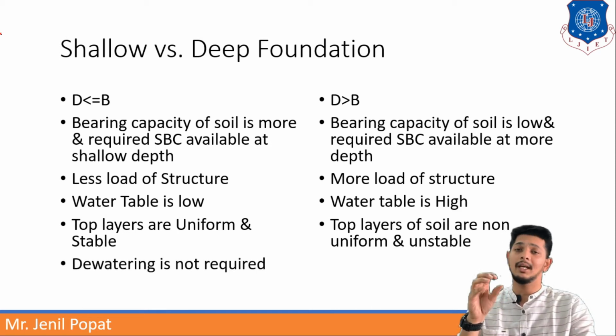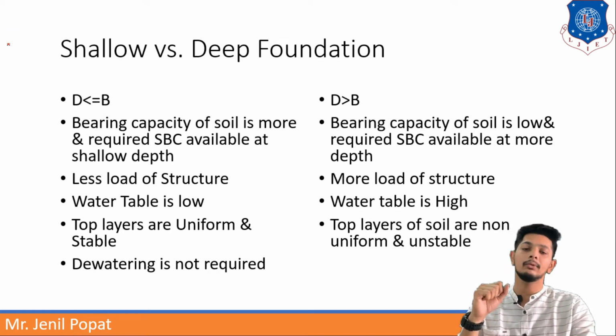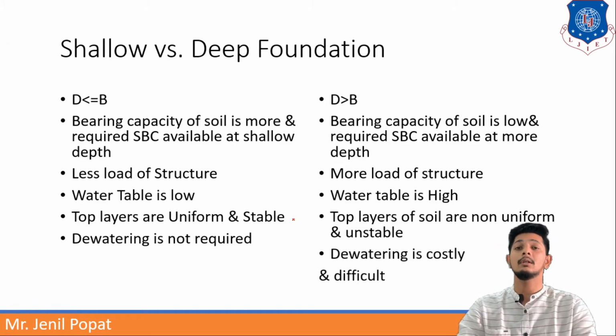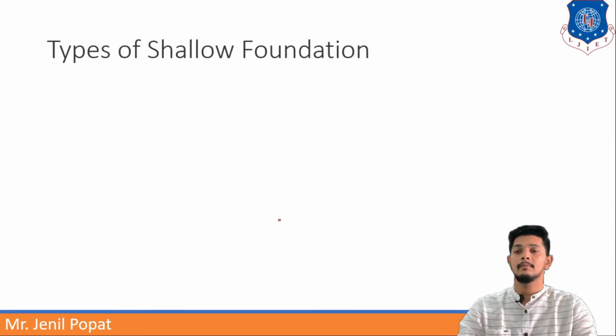Sometimes the moisture content of the top layers of soil is high. In that case, you have to use deep foundations. Dewatering is not required when you use a shallow foundation, whereas in the case of a deep foundation, dewatering is a must, and dewatering is sometimes costly as well as difficult. Let us move forward to types of shallow foundation.